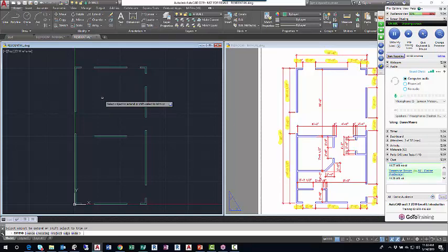Enter. Now everything in this drawing is a boundary. Right? I can extend to anything. I'll hover left at the midpoint and left click the line. When I see the preview, I extend left. Hover right at the midpoint. If I've got a boundary, I'll see a preview. I'll left click to confirm it. Hover, left click, hover, left click. And there's this wall, air quotes, these two lines represent a wall that spans the width of the floor plan.